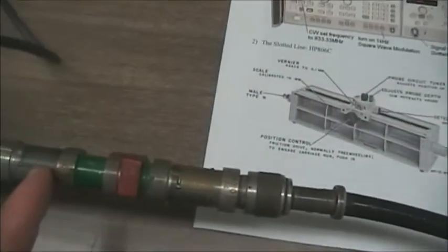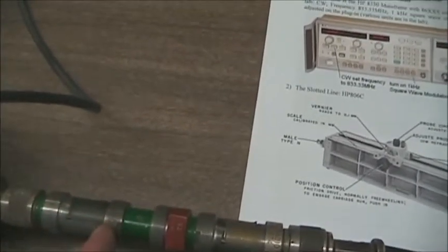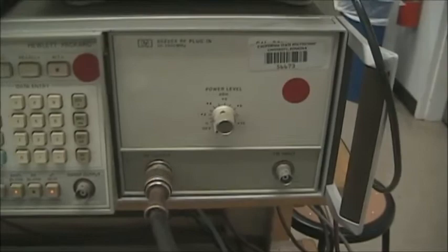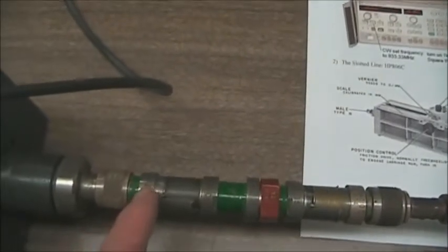On the slotted line, we come out from the generator. Okay, the generator's RF is off right now. It comes through a cable. I have put an attenuator, which is just a signal reduction device, here, and that's mostly to protect the generator. If I had an open circuit, I could reflect back a signal into the generator. So this is an old thing we used to do to protect our generators. Not quite as necessary as that. But we do get a reflection if we have an open.